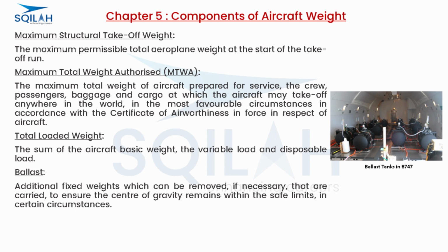Maximum total weight authorized, MTWA. The maximum total weight of aircraft prepared for service, the crew, passengers, baggage and cargo at which the aircraft may take off anywhere in the world, in the most favorable circumstances in accordance with the Certificate of Airworthiness in force in respect of aircraft. Total loaded weight. The sum of the aircraft basic weight, the variable load and disposable load.